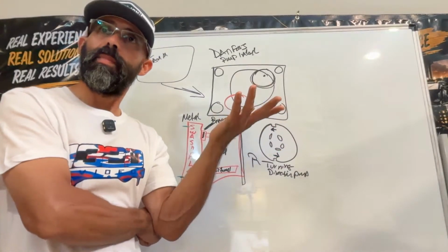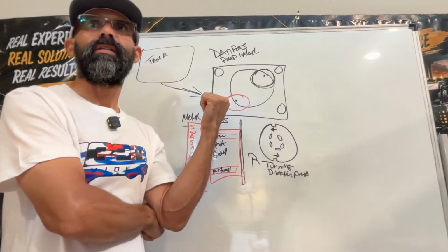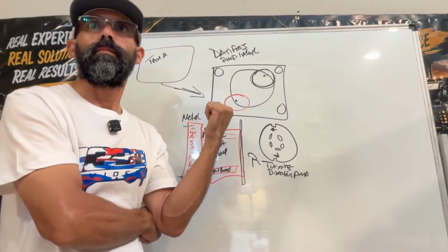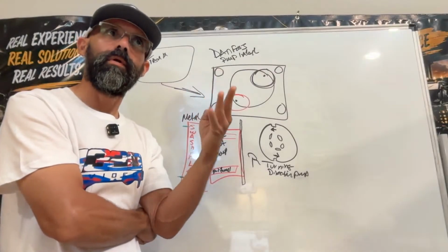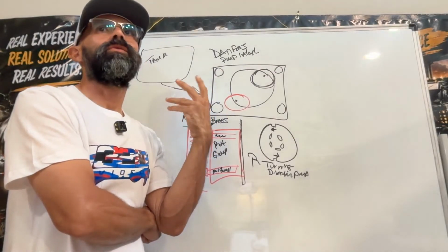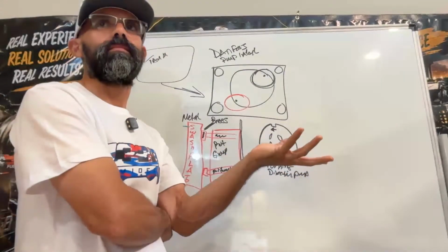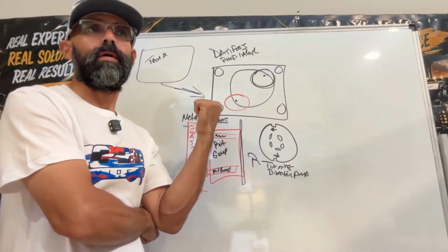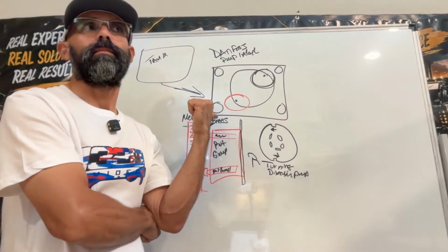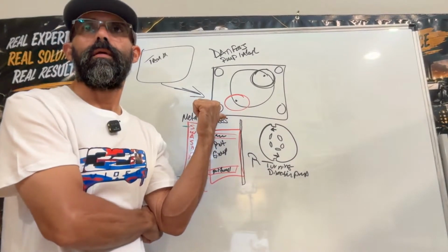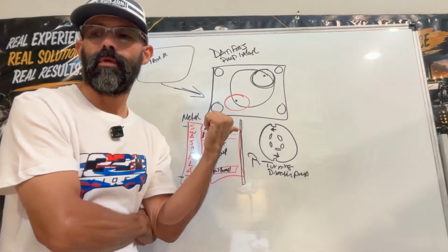And also keep in mind the hydraulic oil needs to be replaced. Hydraulic oil is not meant to last forever, because as time goes on, it starts losing its lubricity, its lubrication properties. It's got its lifespan. So that's something you've got to take into consideration.